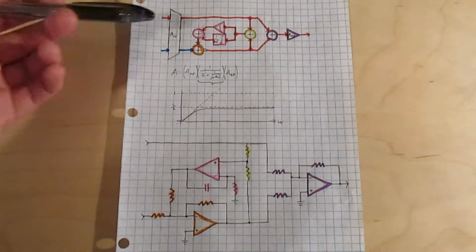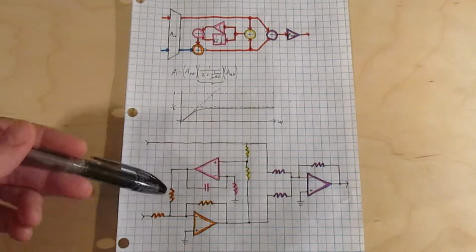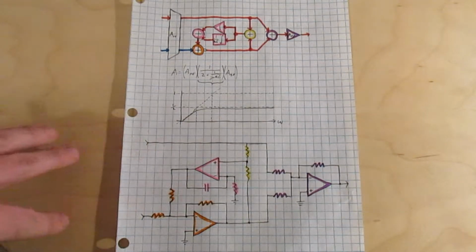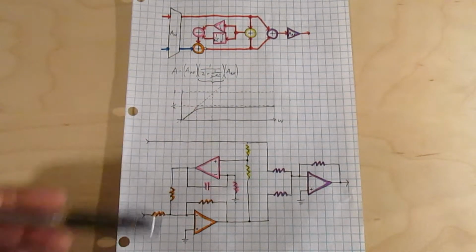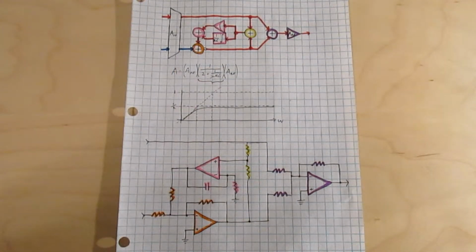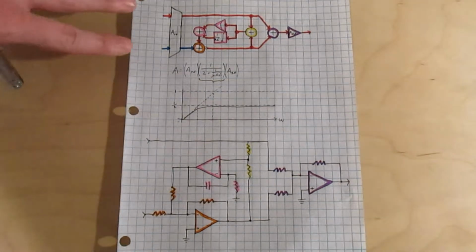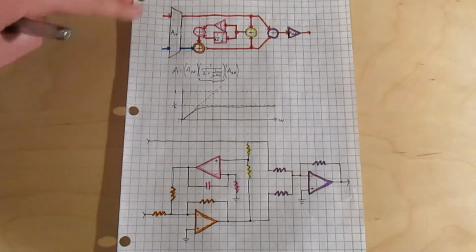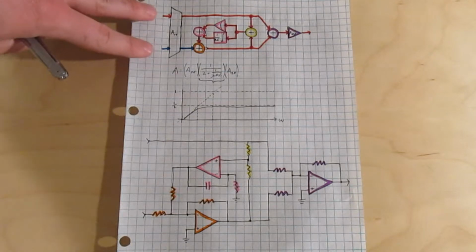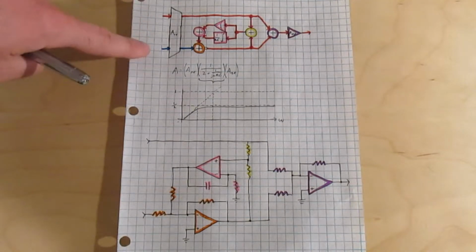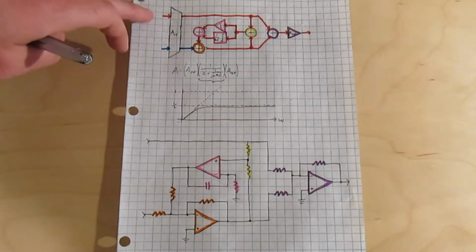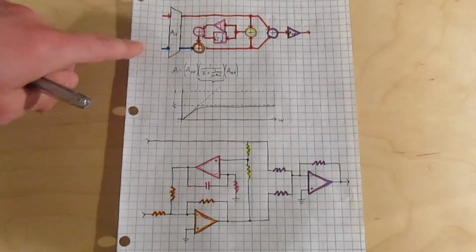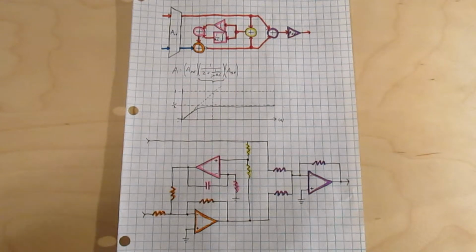And here's a block diagram of Jason Nguyen's circuit, and down here's the schematic. I left the front end off the schematic because it's not too important here. I also color-coded the components in the schematic so you can see which parts of the block diagram they make up. I've also color-coded the signal lines in the schematic with red and blue. If you remember, we have differential inputs, so one signal gets subtracted from the other. The signal with a positive sign gets a red line, and the signal with the negative sign gets a blue line. That's also useful to keep track of which blocks in the block diagram invert the signal.